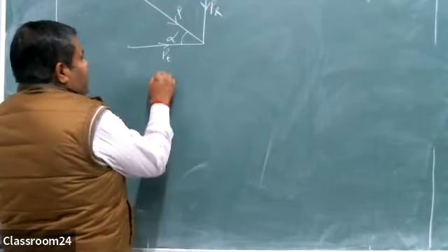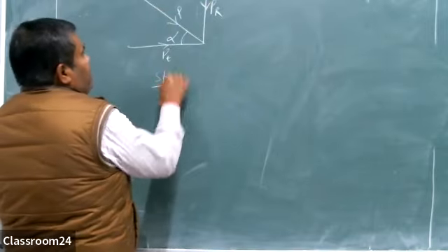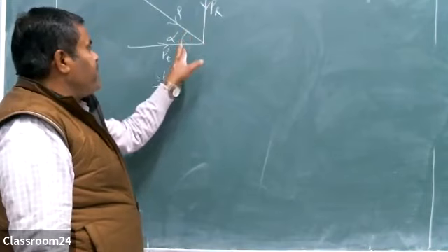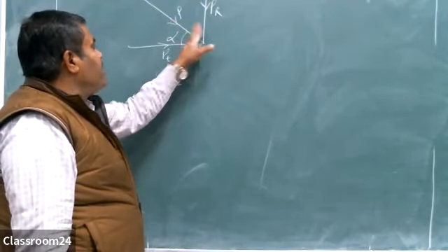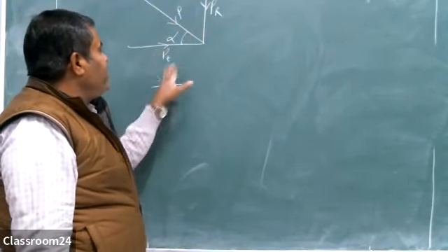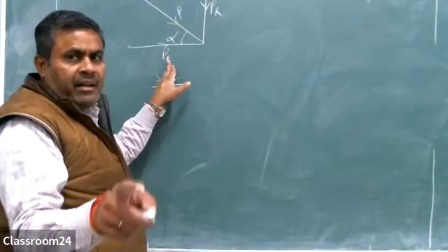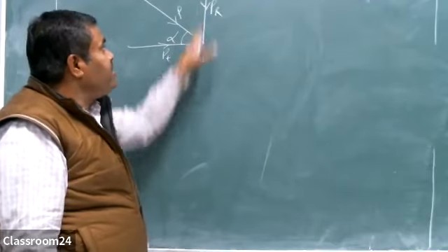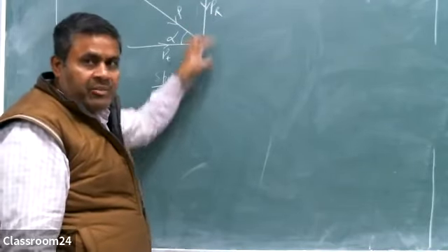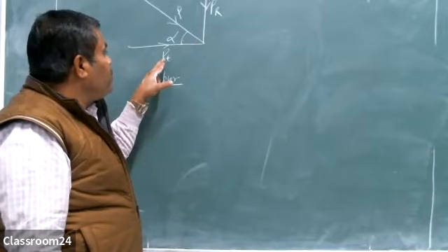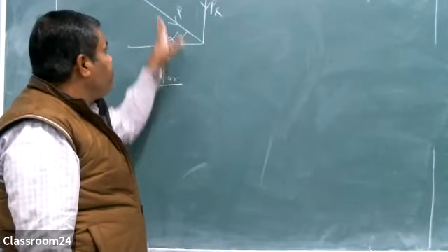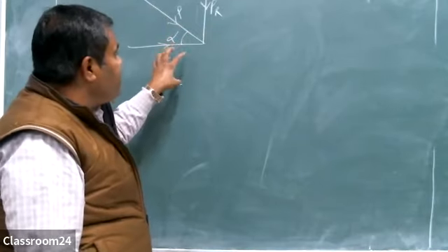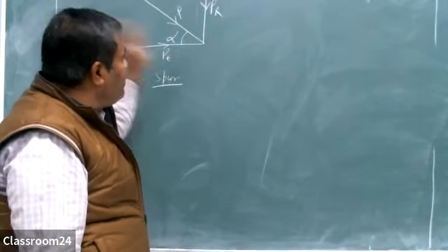So in case of spur gear, ये जो मैंने डायग्राम बनाया है, spur gear force analysis, P is acting at some pressure angle. It is having two components. One is tangential component PT, which is responsible for the bending phenomena of the teeth, and this is responsible for compressive phenomena of the teeth. So P is having only two components in case of spur gear. So this is the force analysis of spur gear that we have already learned.